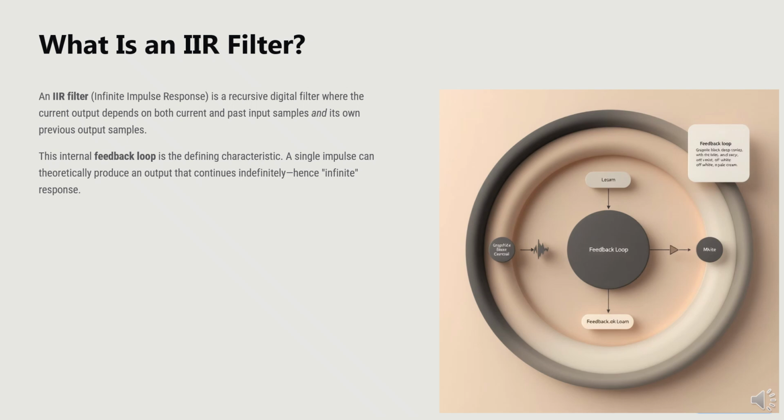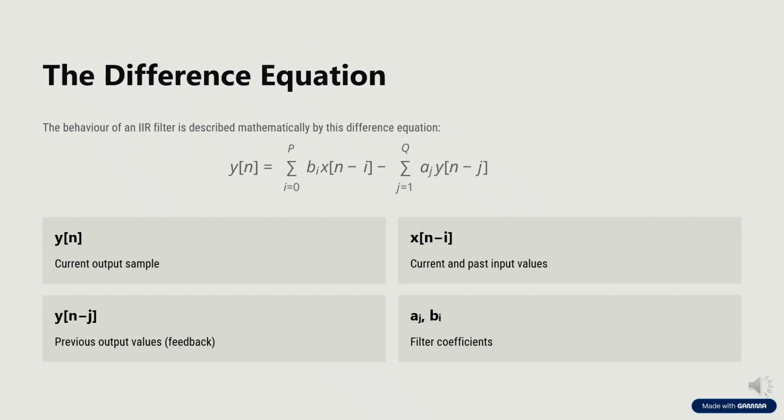The output will continue to fade away slowly, and in theory it will continue to fade away until infinity. It will never be 0; it will always be there. That is why it is called an infinite impulse response, as you are getting a constant infinite output for a given input impulse. Now, I told you that the infinite impulse response filter is a type of recursive digital filter.